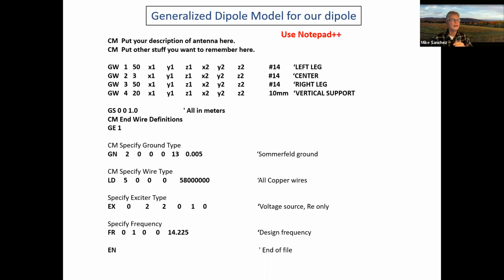For example, if you move the transmitter all the way to the left of the antenna so it's end-fed, you'll see how high the impedance is and how much of a matching section you have to build to actually be able to get it to transmit. So another reason it's dead center is that's the closest you can get to 50 ohms impedance for this antenna.